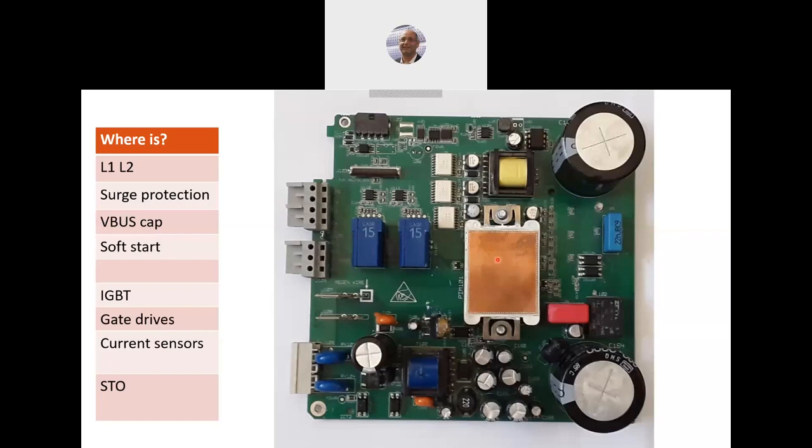On one side is the bus plus, and on the other side is the bus minus. And every one motor phase goes through these sensors and out. Another one goes through these Hall sensors and out. And the third goes without a Hall sensor to the IGBT.